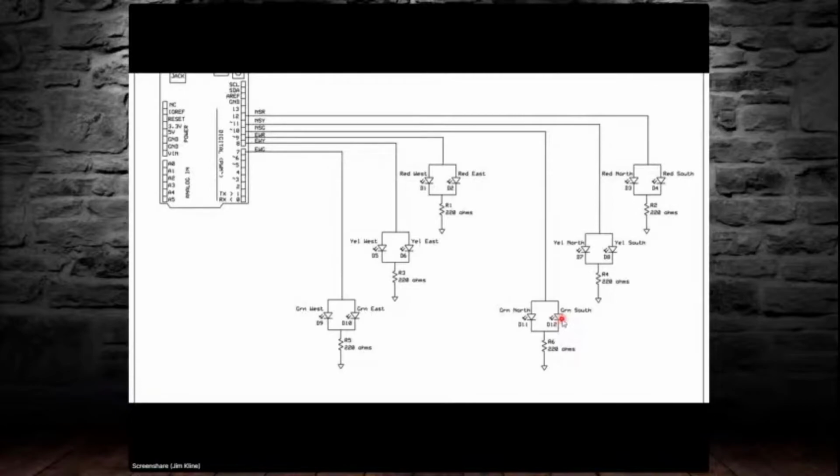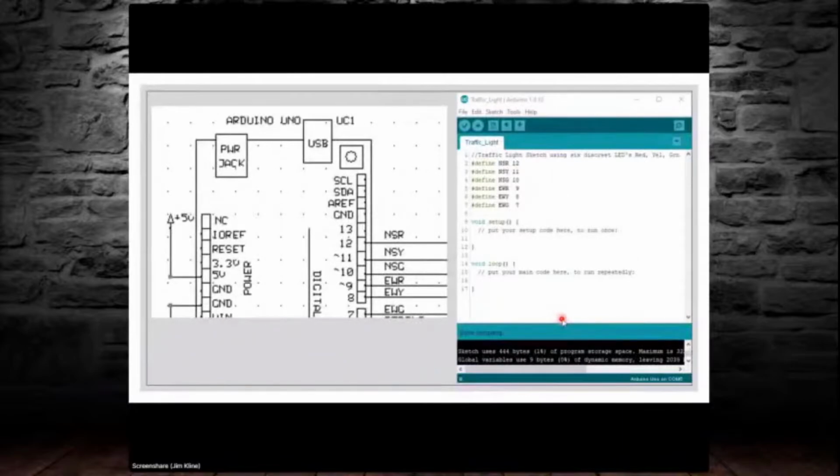If it wasn't made clear before, the Arduino's pins can perform multiple functions, but not simultaneously. For now, we'll just discuss 2 of those functions, and they are input or output. The only way the Arduino knows the function of a given pin, input or output, is when it is properly identified within the sketch. Here is a side-by-side comparison of pin connections to the UNO and the IDE code that assigns the number of the Arduino pin to a text descriptor. We're going to use that later.